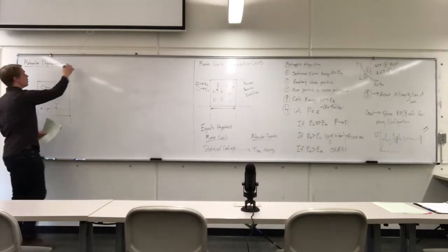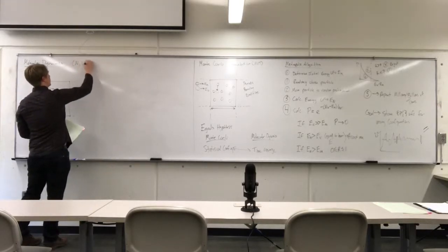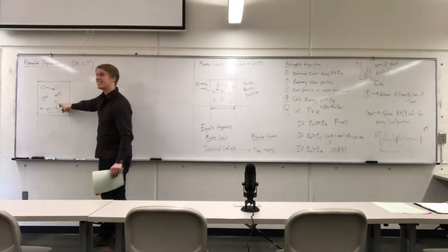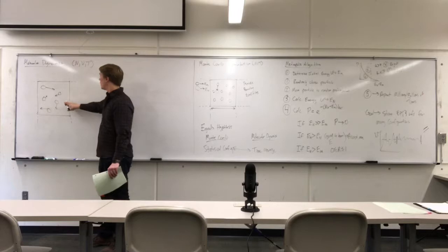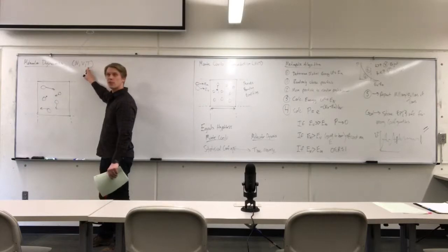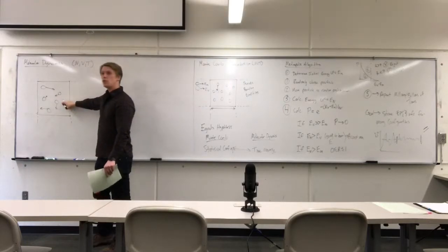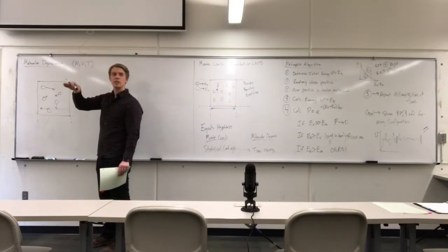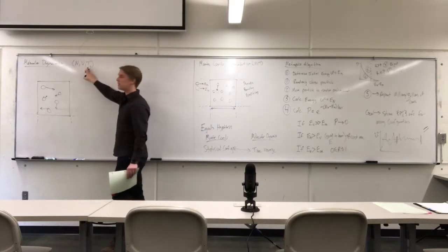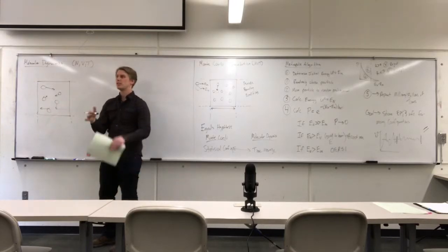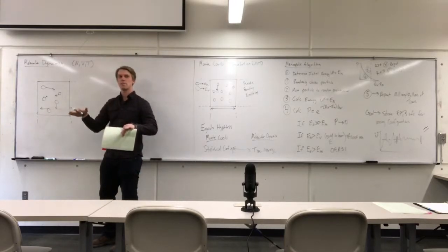So when I perform an NVT simulation, N tells me I know exactly how many particles are in the box. V, the walls are rigid. I'm not allowing them to flex or shrink. T is the tricky one. Because of numerical uncertainty, you'll have drift in your average energy. And so you need something called a thermostat to make sure that after so many time steps, you renormalize all the velocities to make sure that your average temperature is the same.